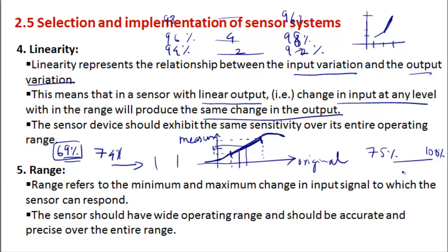That is why you might have heard news wherein people were brought to hospitals. They said that his count, when we took it the first time, was 60 percentage. Within 5 minutes, his oxygen value dipped to 40 percentage. Things like this happen because when you are using a digital pulse oximeter, the range in which it is linearly working is a very small range. Beyond that, the value can be anything. It can be correct, it can be wrong.